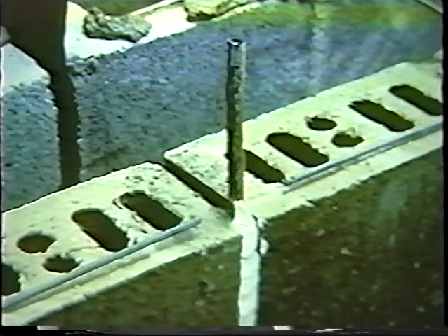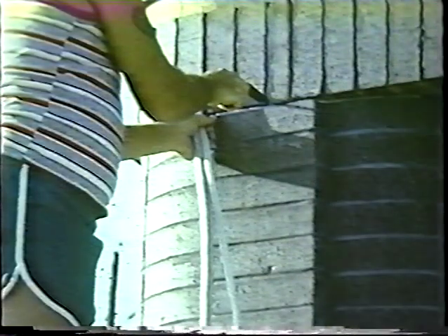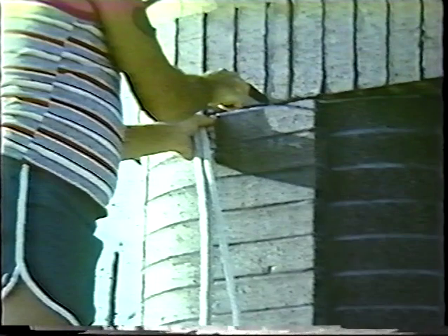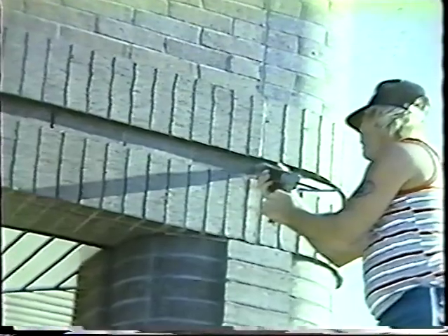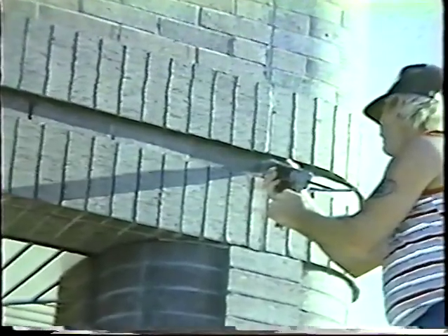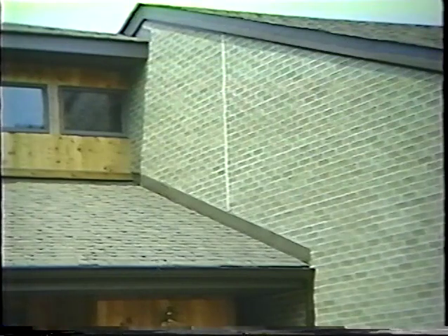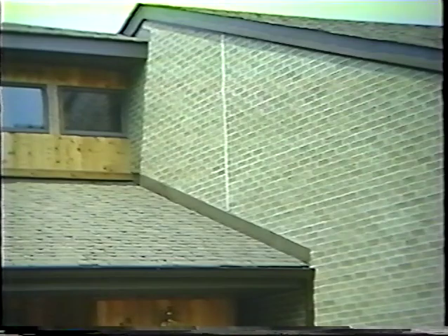Any joint reinforcement should also be terminated at an expansion or control joint. After the wall has been laid up and cleaned, a backer rod and sealant are placed in the joint. A backer rod is a soft foam rod used to keep the sealant at a constant depth. A good grade sealant is then used to fill the joint. If installed properly and at the correct locations, expansion joints can eliminate many cracks in brickwork.